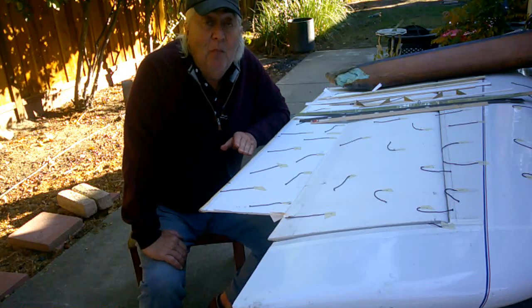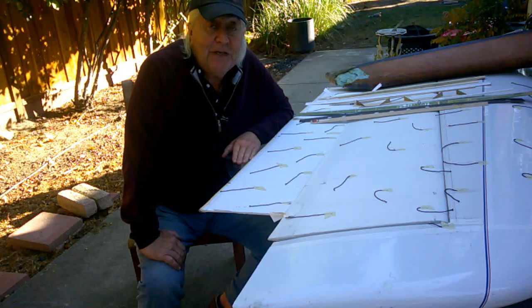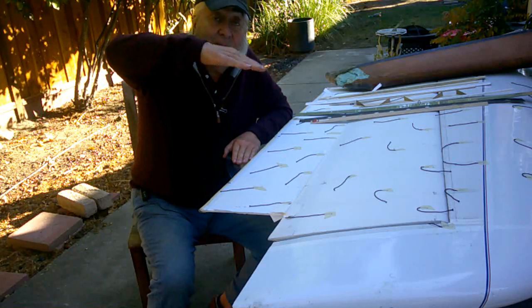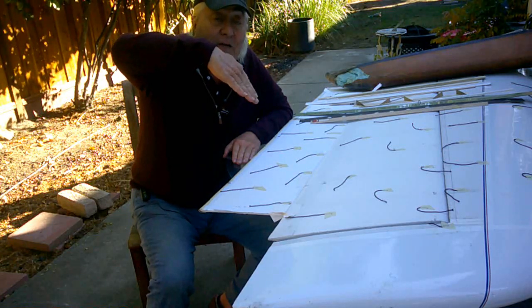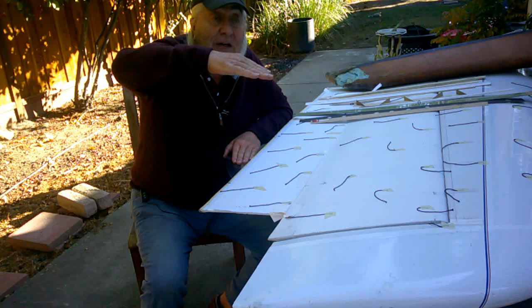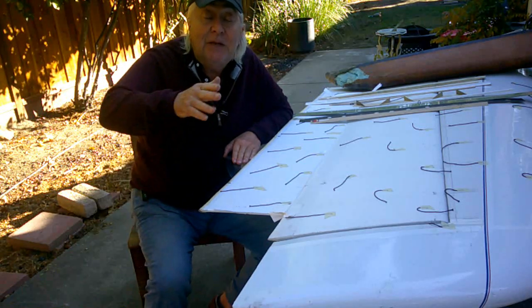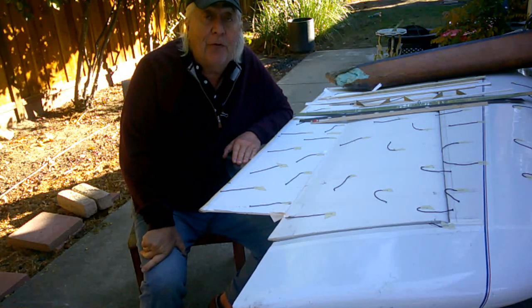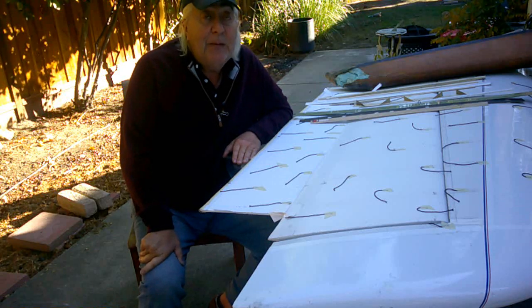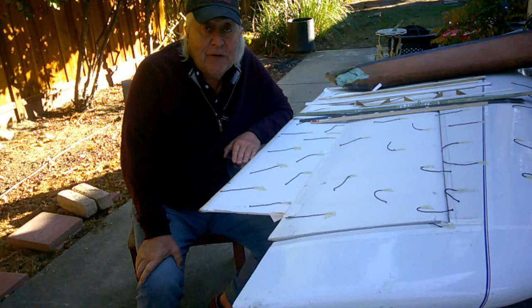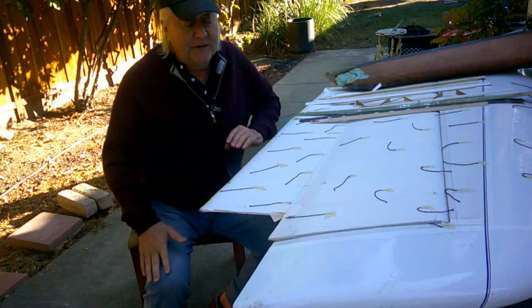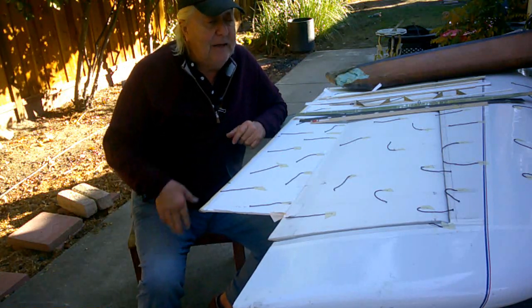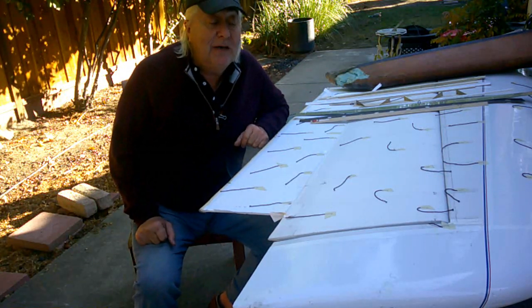And I'm going to need more control surface area, because if I can't deflect my elevon down 20, 25 degrees, if I can only do 15, well then I'm limited in the amount of control authority I can generate. So I make up for that lack of control authority with bigger elevons. And that's where it ended up going.